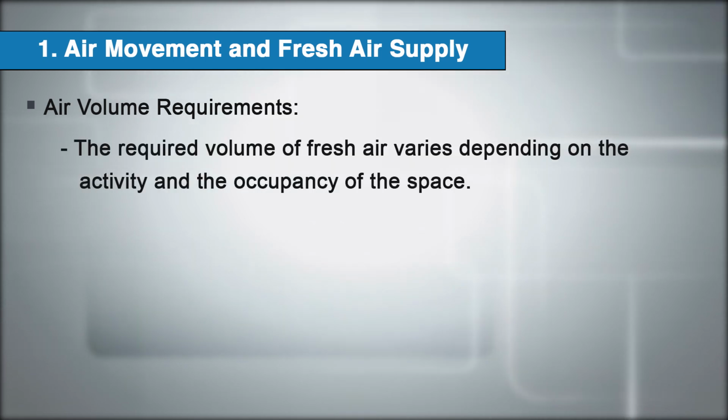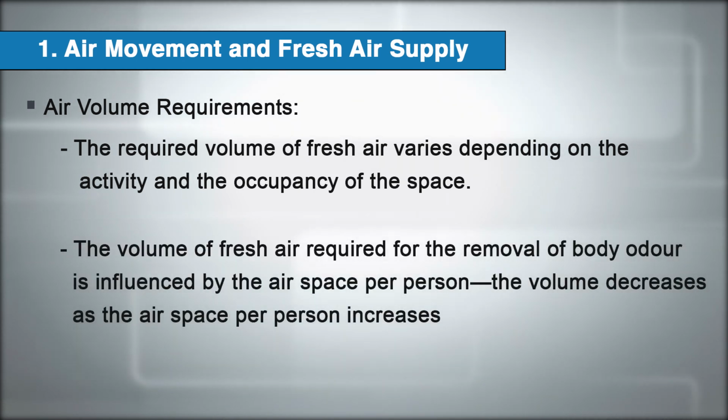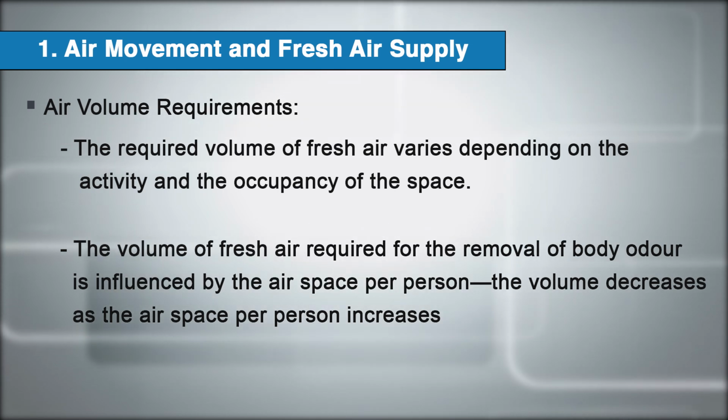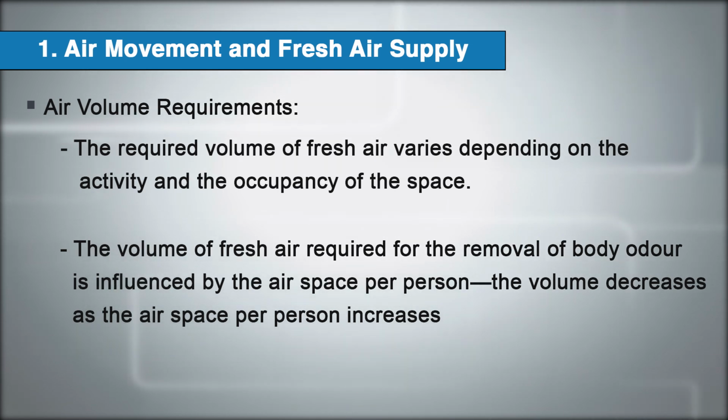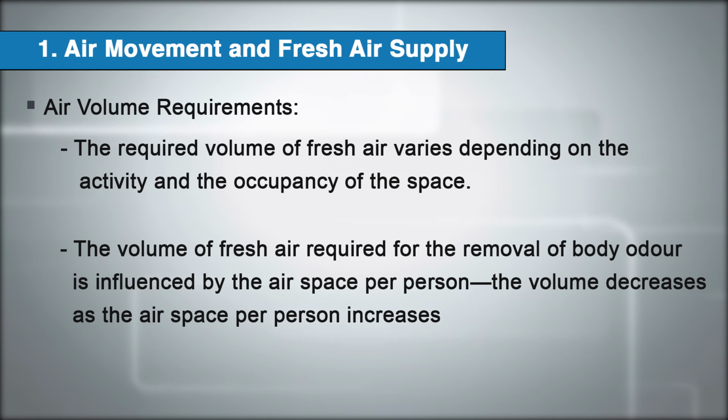The required volume of fresh air varies depending on the activity and the occupancy of the space. For example, the living room and the bedroom typically need a minimum of 3 air changes per hour. The required volume decreases as the per person space increases, with standards adjusting based on the type of building and its use. The volume of fresh air required for the removal of body odor is influenced by the air space per person. The volume decreases as the air space per person increases.